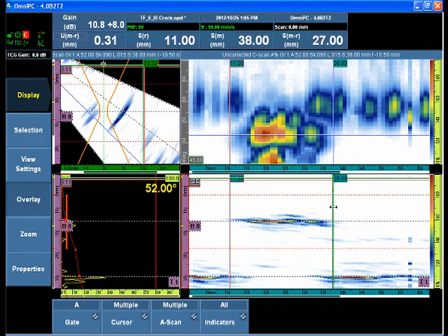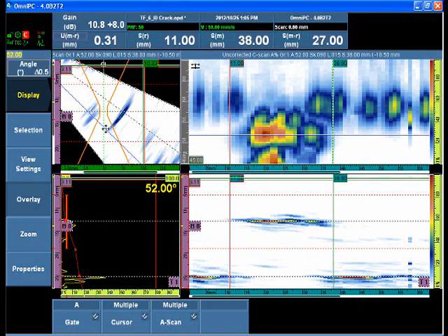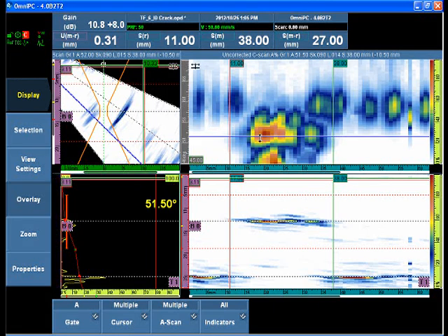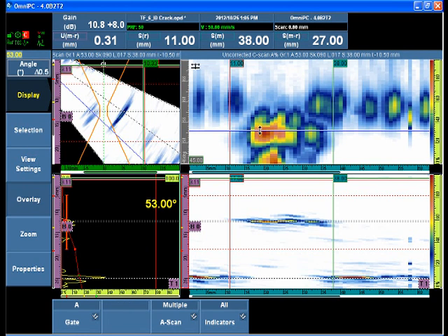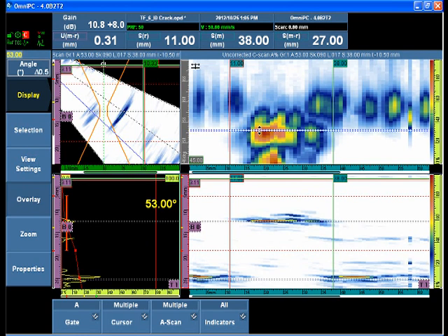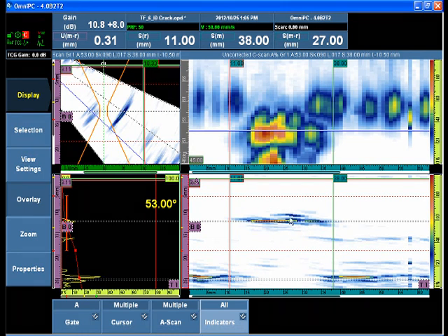and we will identify the right side. So our length sizing at the area where the crack breaks the surface has been identified. Now we can do our depth and height sizing. And again, this projection that we see is at B0 where the crack is breaking the ID surface, and we can see a little bit of projection here of the different facets.